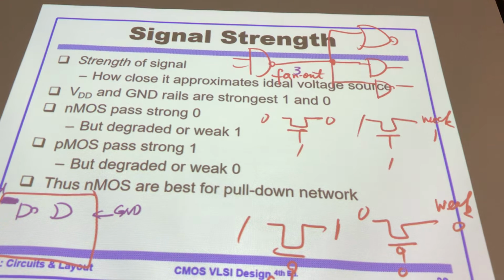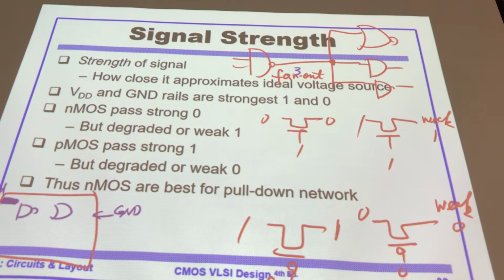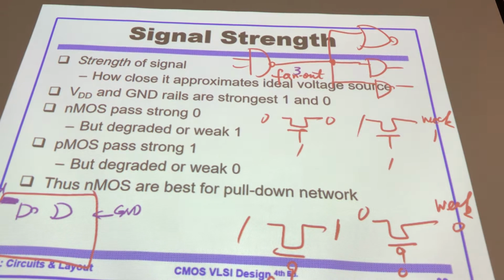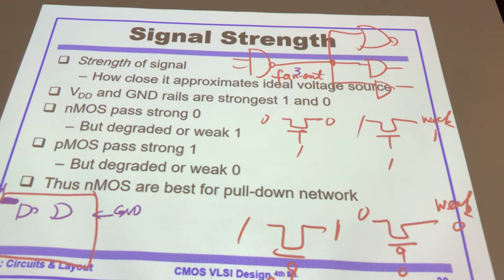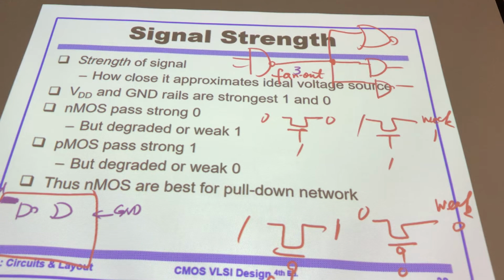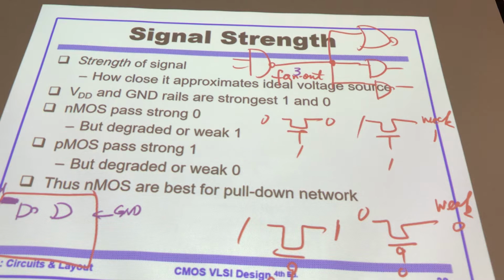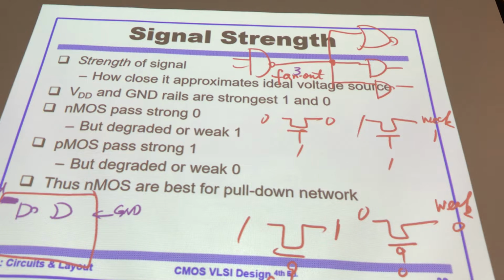If this signal will connect like 3 gate or 4 gate, probably should be fine. But you connect like 10, 20, 30 gate input, you're going to get trouble because signal too weak. It's not going to drive so many gate inputs because the loading too high.